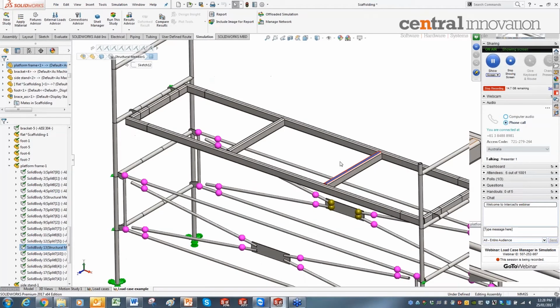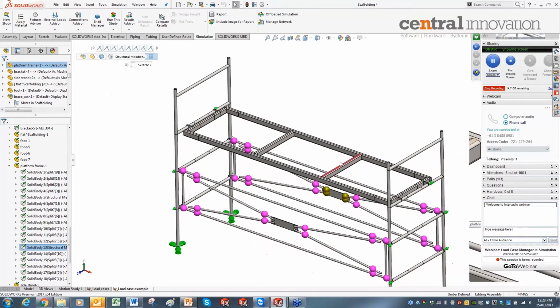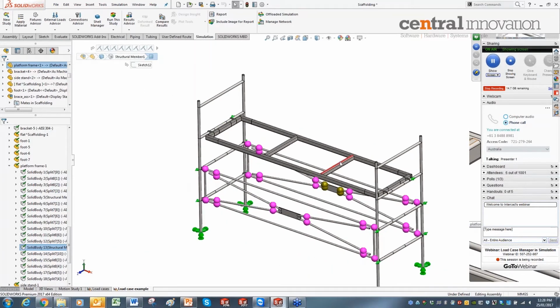The third loading condition is the gravitational effect. I want to include the cell's weight or the gravitational effect. So I'm going to add gravity. And fourth loading condition is mainly to stabilize the model. I have this vertical beams. I need to fix it in the vertical direction.